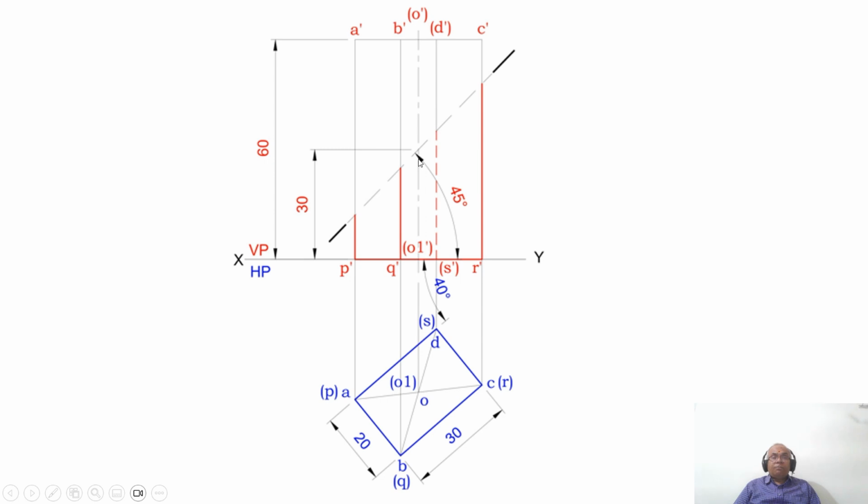Then by using the protractor, with reference to this horizontal line, you measure an angle of 45 degrees and draw an inclined line passing through on either side of the longer edges. This is represented by big dash, small dash, big dash, small dash, like that. Then once you get this point, so these points are here. So now what I need to do is darken this.